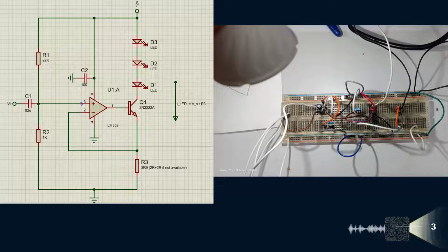The internal resistances are tens of megaohms, and the resistor should be limited to the range of 1K to 680K for op-amps built with FETs, which have higher input resistance. Resistances can be several megaohms, which in practice are the highest resistance available. The purpose of C1 is to prevent the audio source VI from short-circuiting R1, effectively removing V bias. Capacitor C1 blocks DC voltages and low frequency AC voltages.